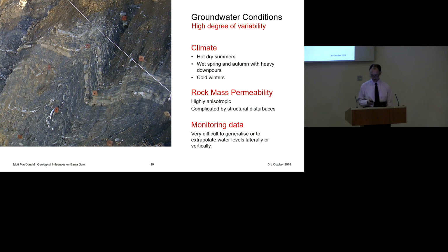So if you look at that slide, you'll see that the material to the top and the right of this sort of folded band is slightly darker, it's slightly wetter, it's actually damp, whereas the material below and to the left of those beds looks as dry as a bone, which it is. I'll just point out there's a little drain pipe there. That drain pipe used to produce a little bit of water.